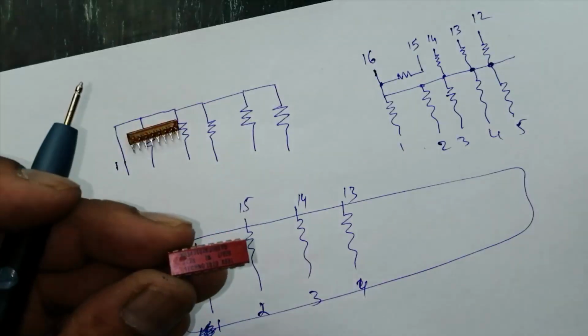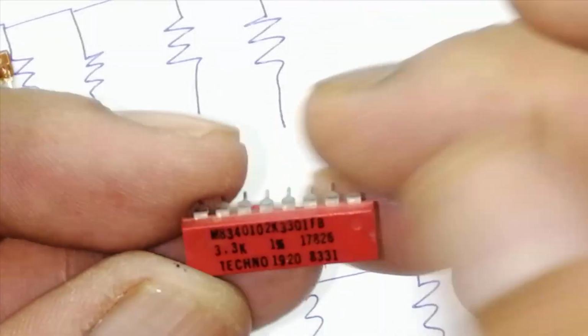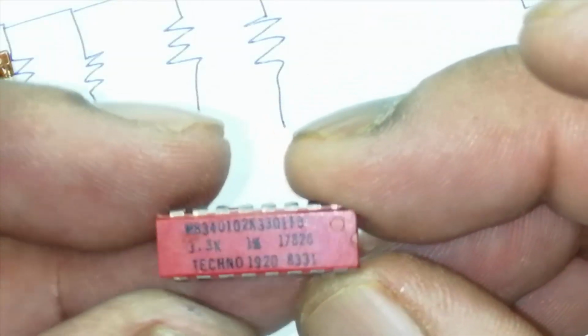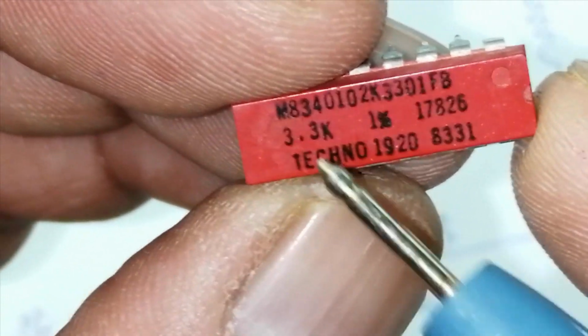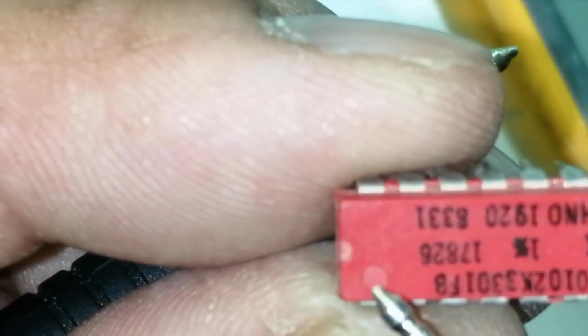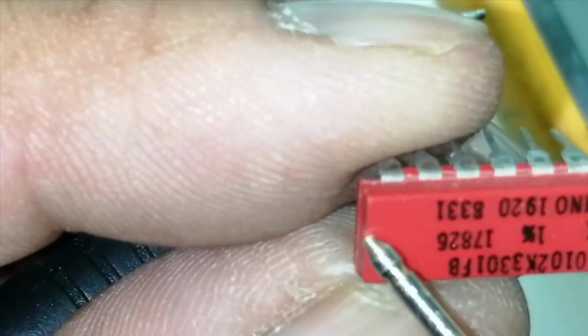Then we see the IC shape. It is not an IC, it is a resistor pack, and there is a value of the resistance mentioned on the component. It is 3.3K. So every pack has its pin identification. If you go to the part number mentioned on the component, then you can find the data sheet, and here pin number 16 is the common pin. So index pin, pin number 1, is here in the dot, and this is the left identification. So pin number 16 is here, pin number 1 is here.